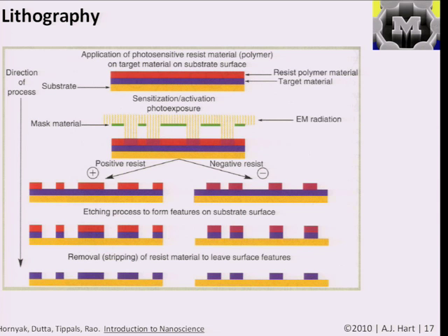After you have this pattern in your resist, you etch into the next layer, for example, using a chemical or using an ion etch. It could be, for example, exposing it to a gas, or a gas with an applied voltage to accelerate the ions toward the substrate. Then you can create the structure in the second material as well. Then you could do what's called strip the top layer, remove it. You could dissolve it in a chemical that just removes the photoresist, and then you end up with your pattern in the bottom substrate.